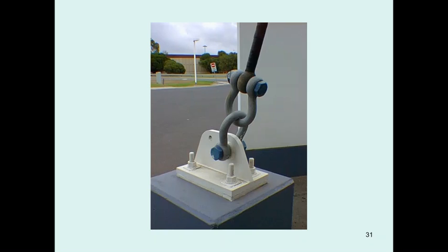I hope you caught some important points, such as why we test steel in tension and why we test concrete in compression. During testing of steel in tension and compression, what should be aware of, such as the eccentricity of the loading. We are supposed to put the applied force passing through the centroid of the section.